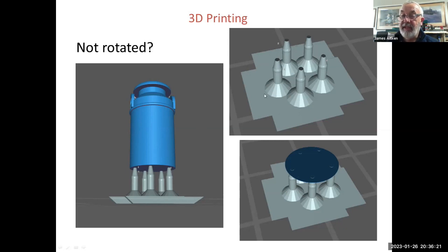And you can imagine as that is built up, you've got your base, which is fixed to the build plate, and is usually bigger in area than the thing you're trying to make, because you can pretty much guarantee it'll stick, and its stickability is greater than the force required to pull the next layer off the build. And you can see, okay, so we've got our 5 supports coming up towards the first layer, and then bang, the first layer is a complete ring.